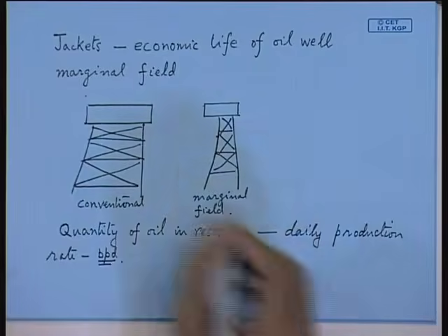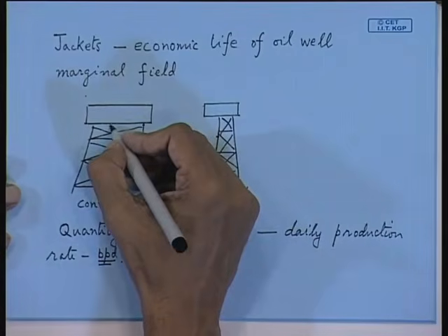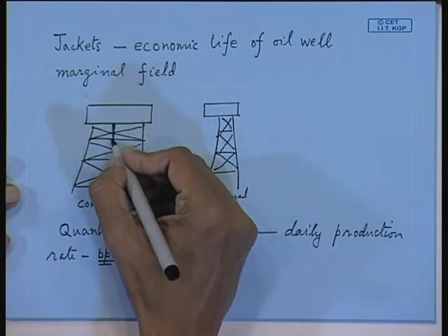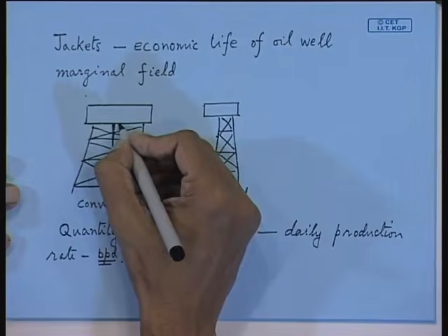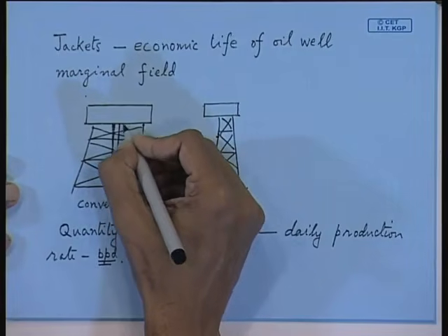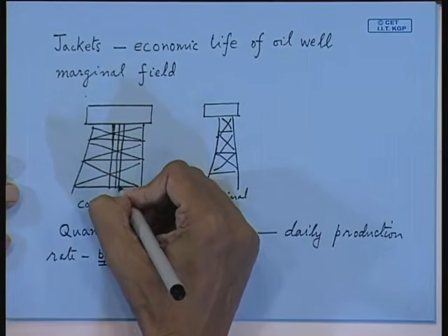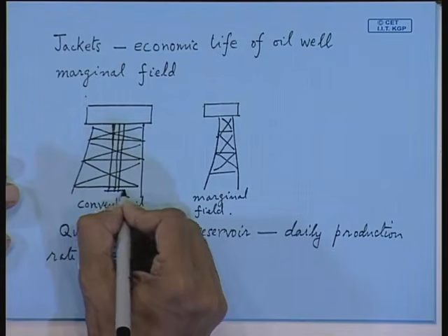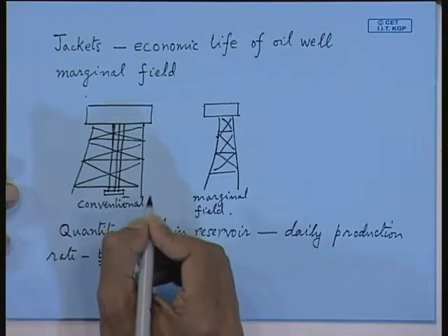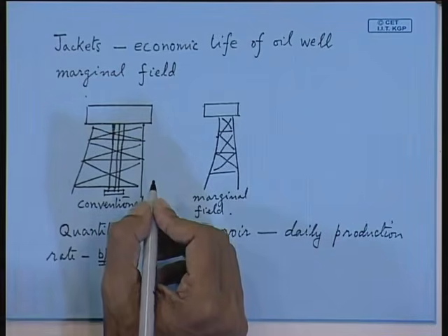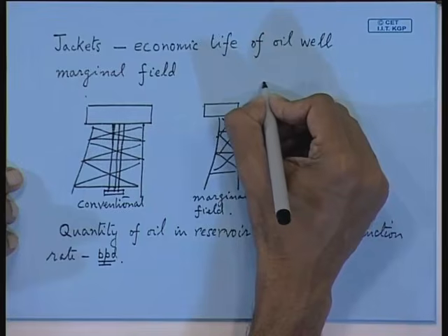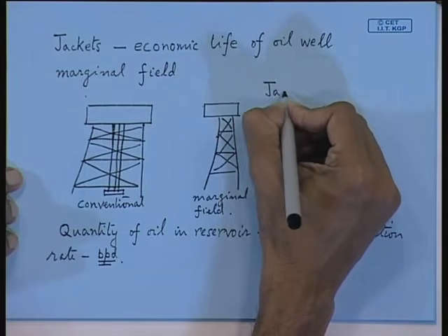Why? Because the higher the rate, that means your marine riser or conductor pipe is going to be of a larger diameter. So, the supporting facility will also have to be more robust to take account of these marine risers. So, the jacket also provides support to marine risers.